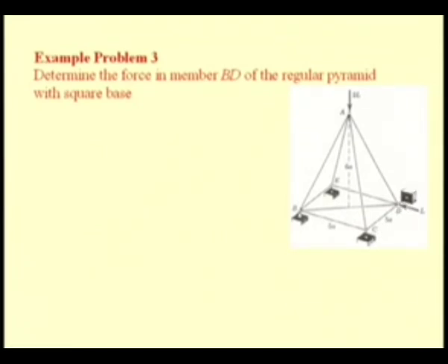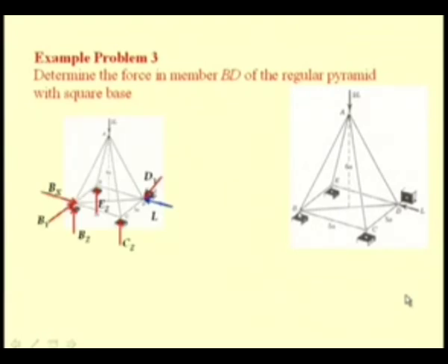First, let us see if this problem is statically determinate externally. In order to do that, we have to construct the free body diagram of this truss. Since at B the truss is pinned, it arrests all translation and thereby provides 3 components of reaction Bx, By and Bz. And at C we have a slender vertical rod, thereby the member can only support a vertical reaction and thus offers only a vertical component of reaction Cz.